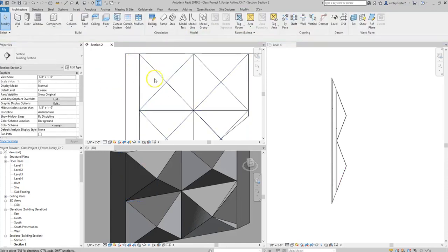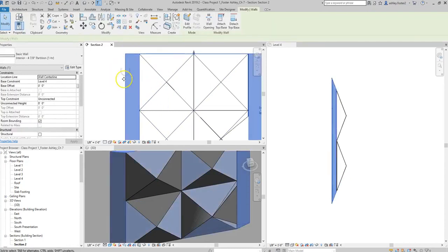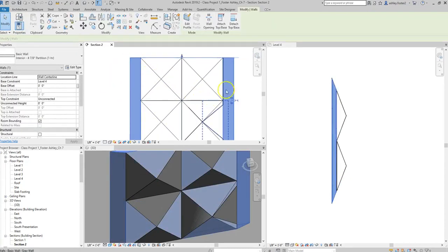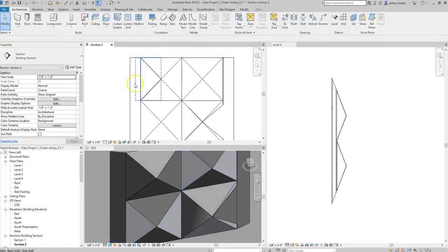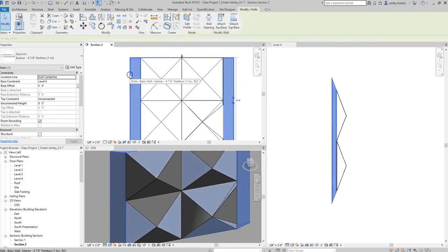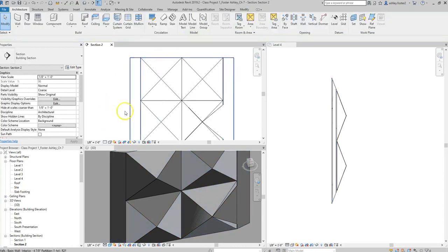So as you can see, when I finished fixing that wall panel there, this wall is still a little messed up. And we can fix that at the end here, but it's the same concept. You just select the wall and you'll click Edit Profile.